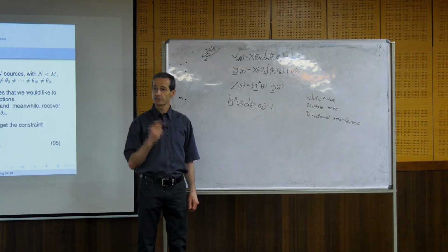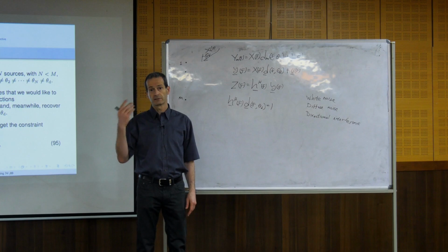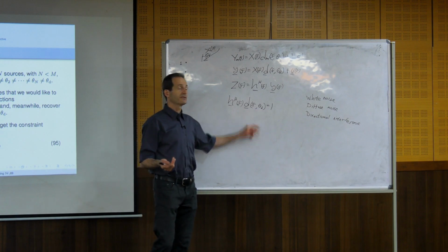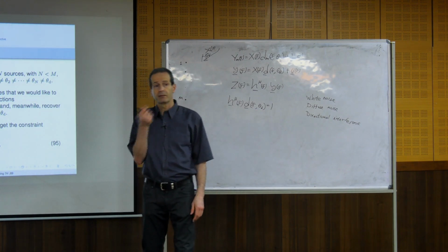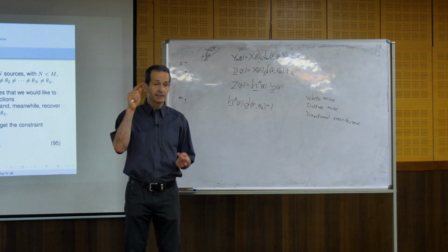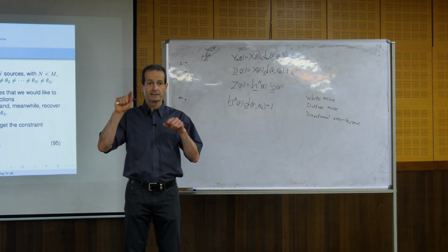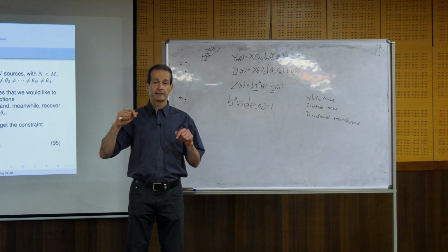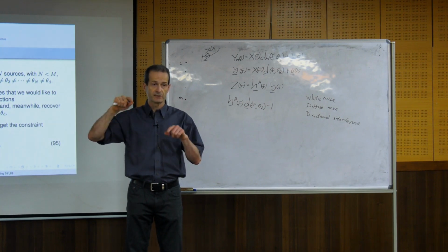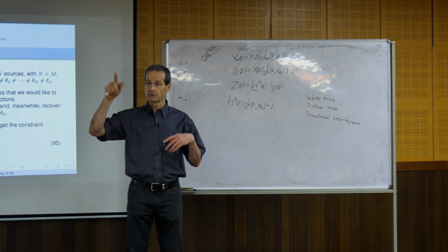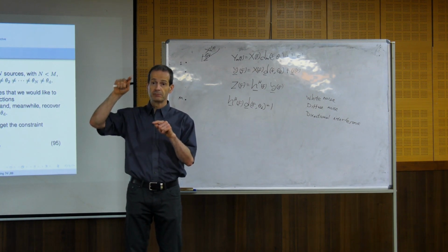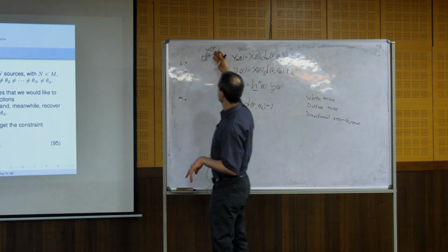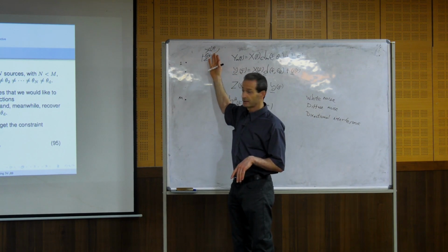If you have another suggestion for a constraint, you need to think: is it possible? What does it need? But if there is a signal that comes from this direction, and I don't know anything about the signal, I cannot use correlations between sensors regarding that specific signal. Okay? So in the time domain, we use correlation matrices of samples. In the frequency domain, we use correlations between sensors relative to the desired source. Okay? So we called it